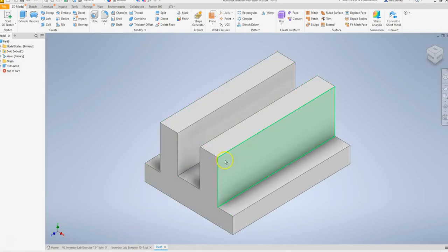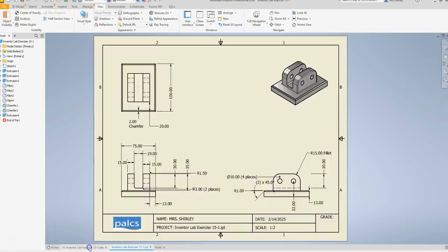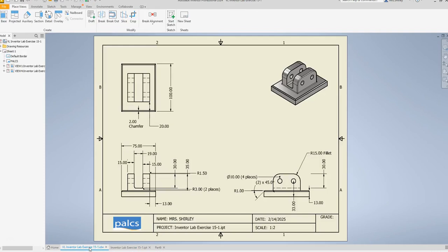Now we have to cut it back. So if you remember in Intro to CAD, we did the additive and subtractive method. So we are now going to do the subtractive method so that we have this part cut out on each side. All right, so let's see what is our number that we need to come back on for our extrude. And the answer for that is 20. Right here is 20.